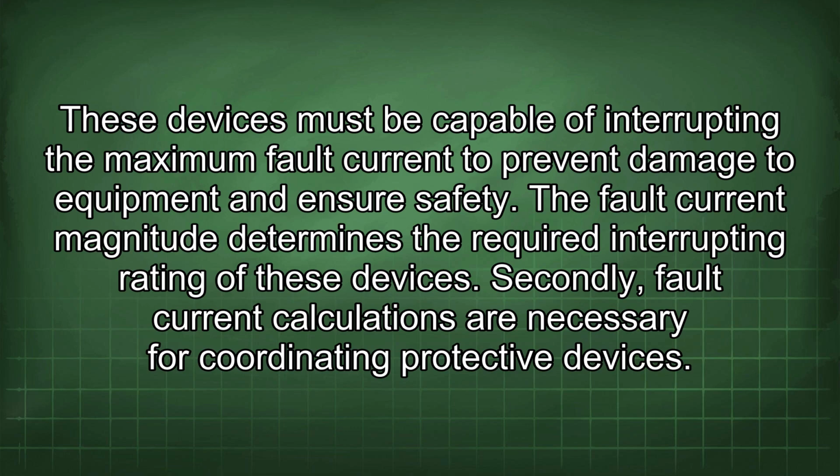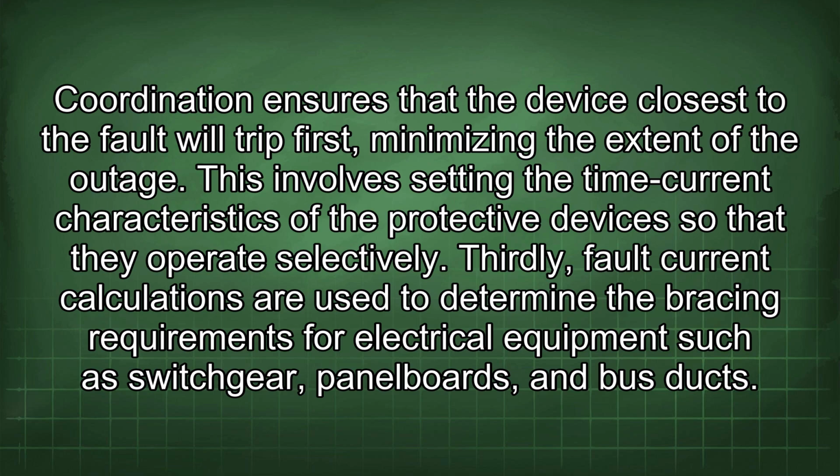Secondly, fault current calculations are necessary for coordinating protective devices. Coordination ensures that the device closest to the fault will trip first, minimizing the extent of the outage. This involves setting the time current characteristics of the protective devices so that they operate selectively.